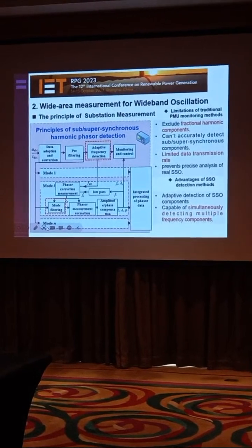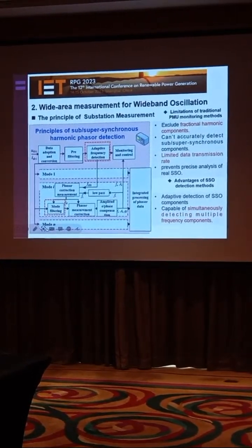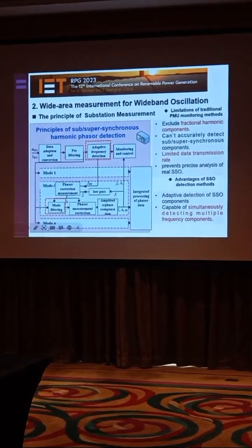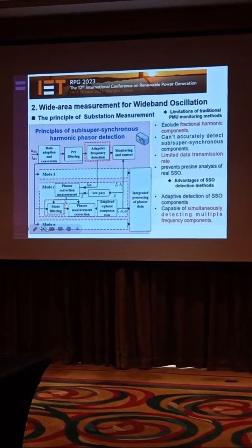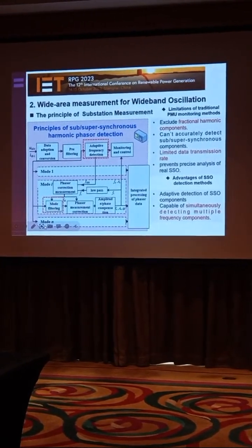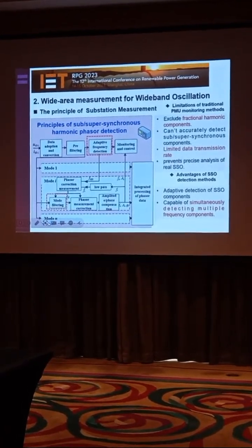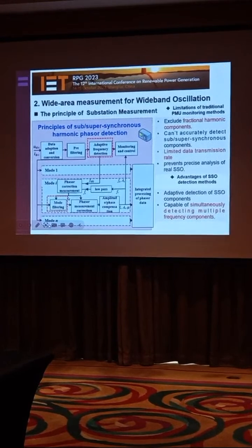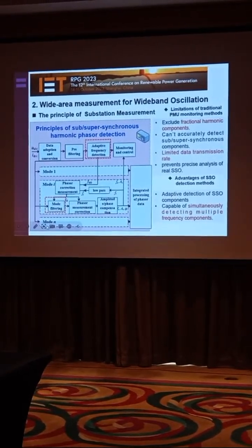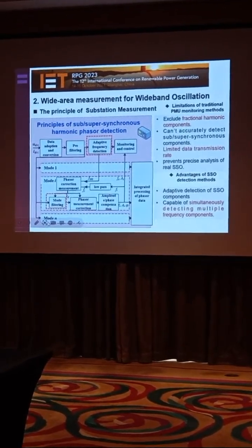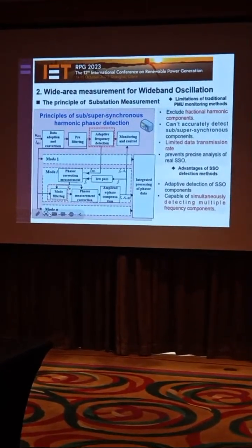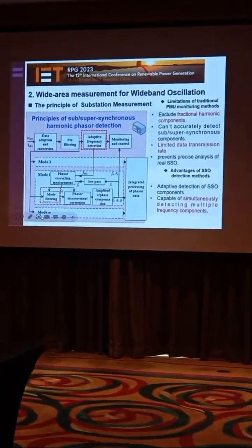Considering subharmonics, it can accurately detect sub or super synchronous components. And the data transmission rate between the substations and the master stations is high, ensuring that the master station can accurately analyze the actual synchronous oscillation.